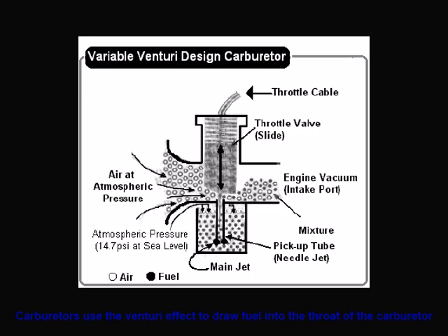In carburetors, the Venturi effect draws fuel into the airstream. As air accelerates through the narrow section, pressure drops, causing fuel to be drawn from the float chamber into the combustion airflow. This principle is vital in understanding mixture control and engine performance.